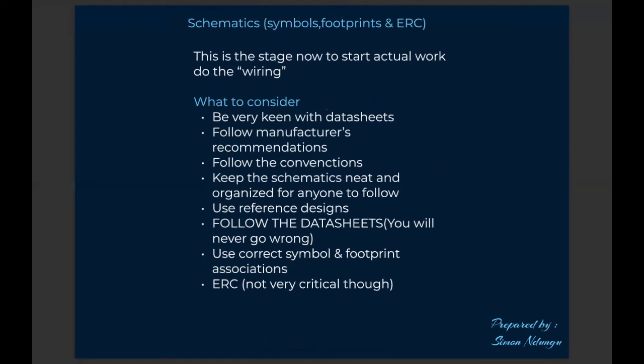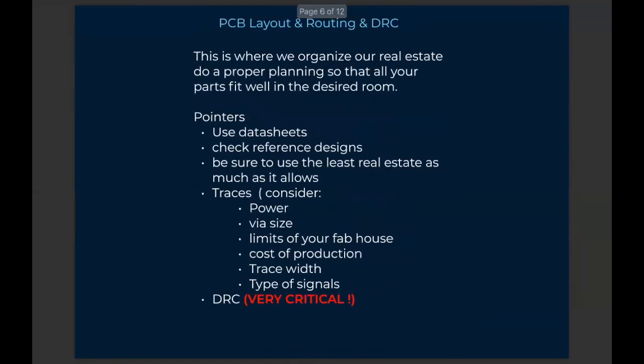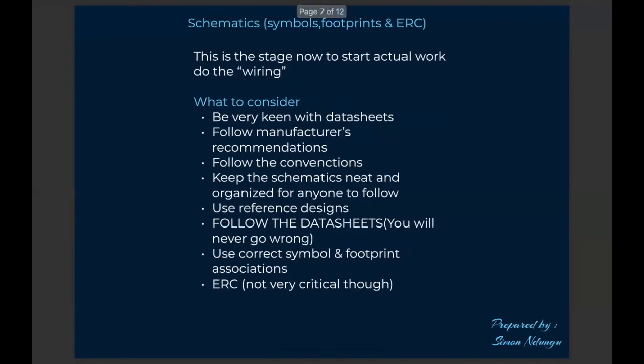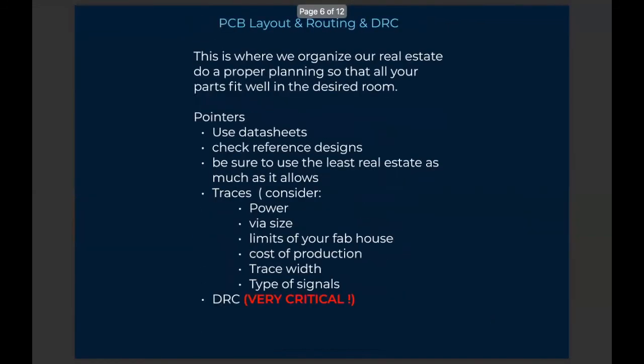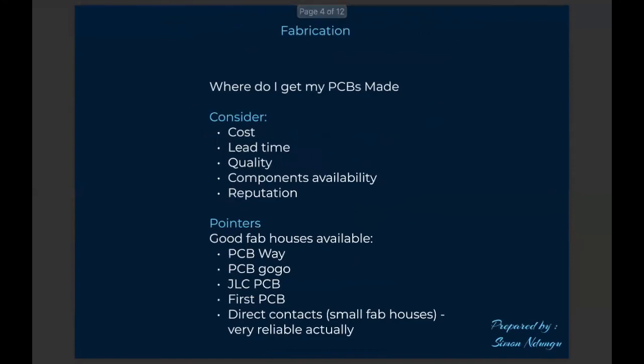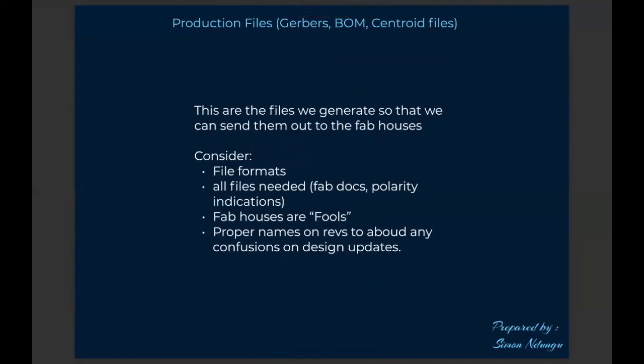Because if the design is not coming back to you, then you really don't have to bother yourself with the electrical tests and stuff. So in most cases, you might find that most of your designs will end up here at production files: once you give your client your Gerber files, the BOM and the centroid files, they can go in peace, and you can proceed to the next project and do the same.